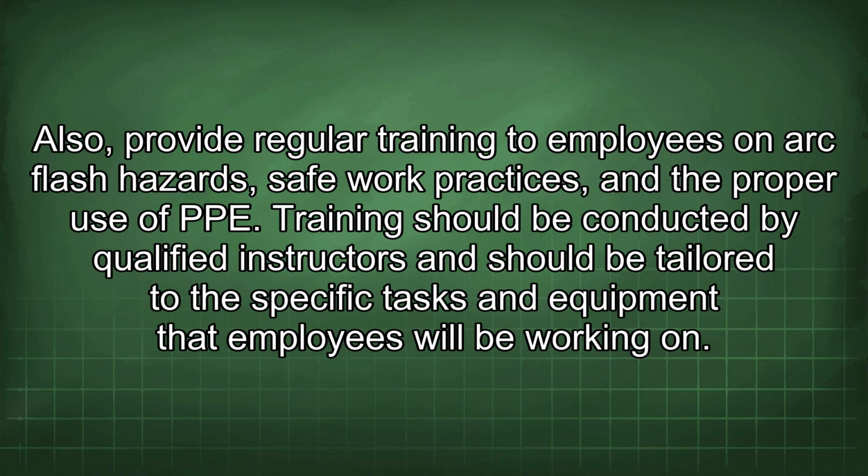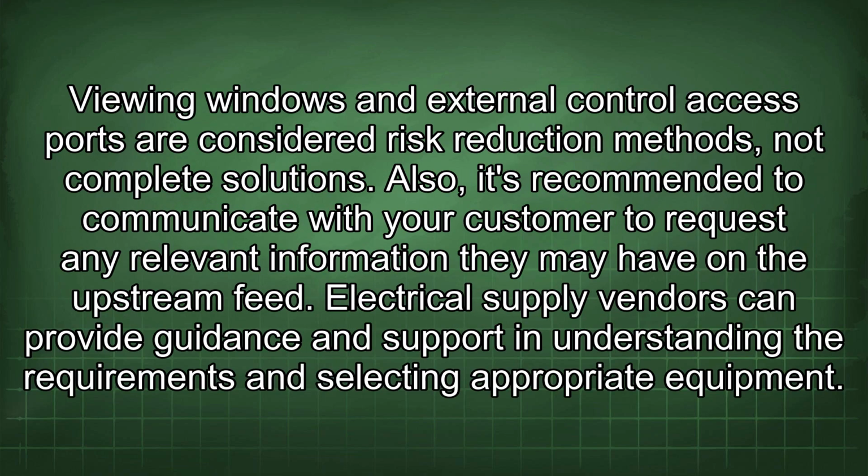Also, provide regular training to employees on arc flash hazards, safe work practices, and the proper use of PPE. Training should be conducted by qualified instructors and should be tailored to the specific tasks and equipment that employees will be working on. Viewing windows and external control access ports are considered risk reduction methods, not complete solutions.